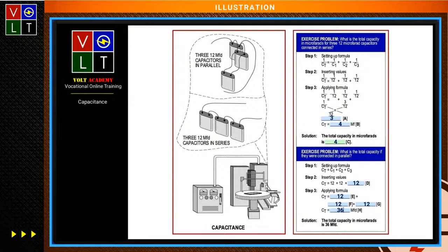Yeah. If you go to the 70E document, we tell you when you're going to work on it that you have to release the power off of those capacitors before you work on it. That's to ensure electrically safe work conditions. That's correct. And when I was teaching, when we go out for an FBA and I do a 70E course, we go through and explain that this is another source that could get you, and therefore you have to drain that off to ground.